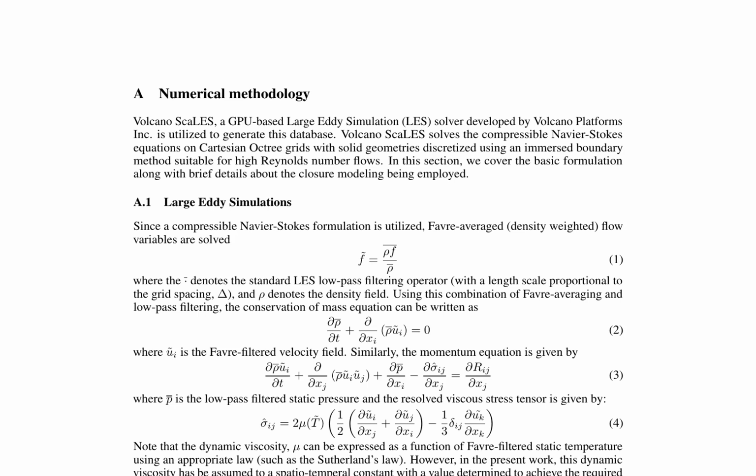The numerical methodology employed for generating the database leverages Volcano Scales, a GPU-based large eddy simulation, LES, solver. This involves solving the compressible Navier-Stokes equations on Cartesian octree grids with solid geometries discretized using an immersed boundary method. The formulation is based on Favre-averaged flow variables, ensuring conservation of mass and momentum.